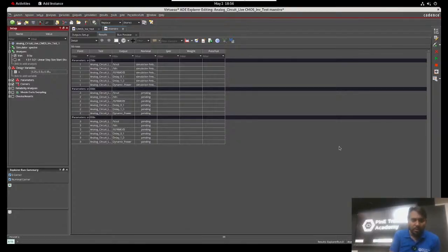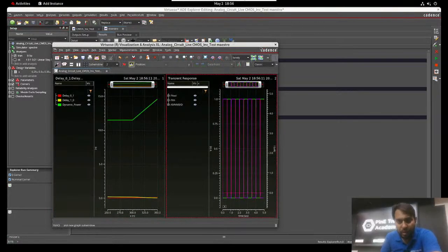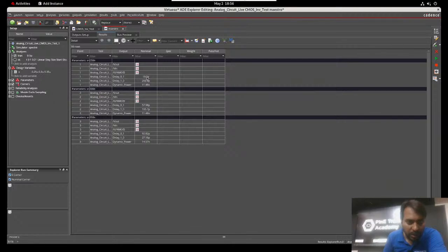So these are the requirements. I am just taking this: 19.2 picosecond, 0 to 1, this is 20, this is 57, and that 165, 90 to 27. So you can make a trade-off. Which one is better depends on the design-specific requirement of the rise delay or fall delay, and on that basis you have a power dissipation: 11.48 nanowatt, 11.48 nanowatt, and 14.57 nanowatt. I hope it is enough for today.